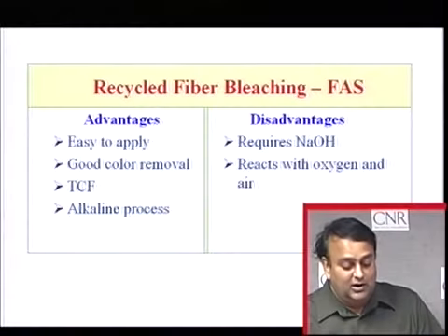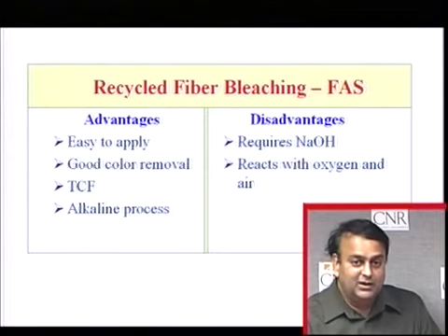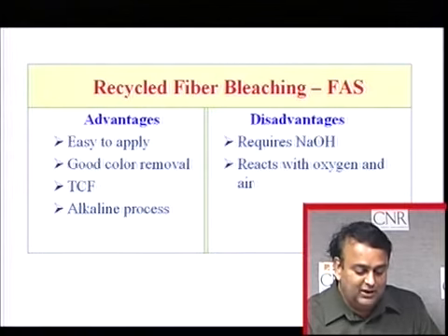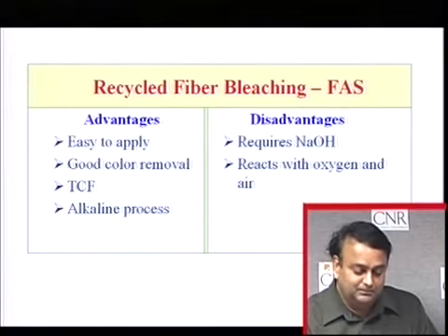Disadvantage, it requires another chemical, sodium hydroxide. Again, like any other reductive chemical, with the oxygen and the air, it reacts and you have less FAS available for bleaching. So you need a flow tower for FAS.